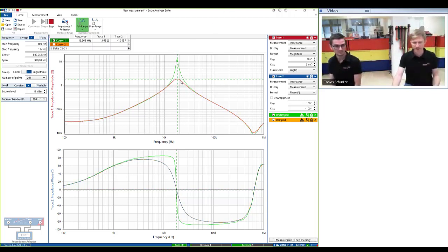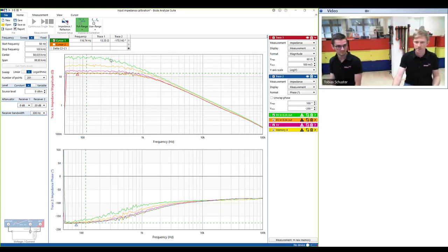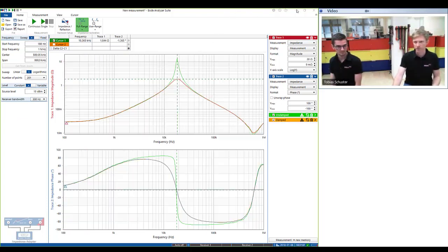So now we know how we can damp the input filter to avoid the peaking. And if we look at the previous measurement, so when I switch to the previous measurement, then you can see that the impedance is coming towards 10 ohms if the input voltage drops. And the peaking of the input filter is going above 10 ohms in the undamped case. So that's where we do have the issue between the input filter and the input impedance of the power supply. And to show that issue, we're gonna do a loop gain measurement now and a transient response measurement.